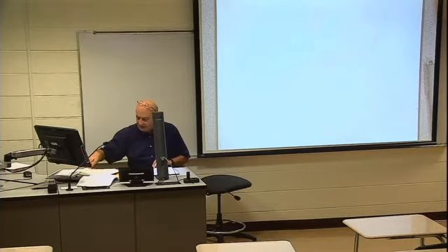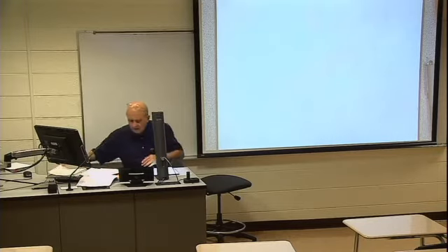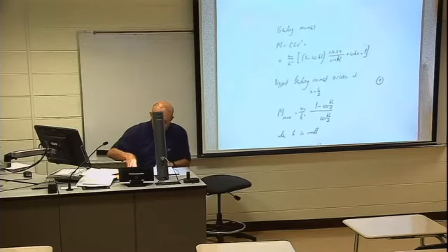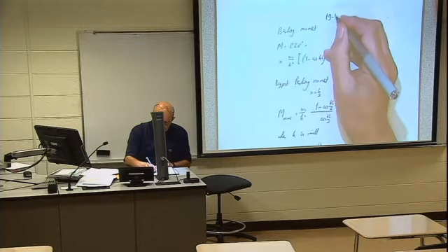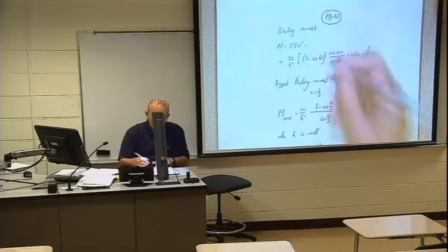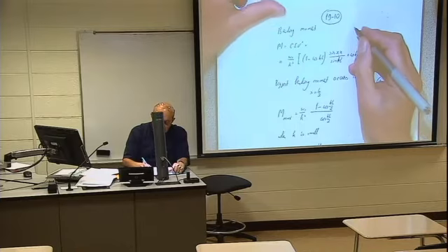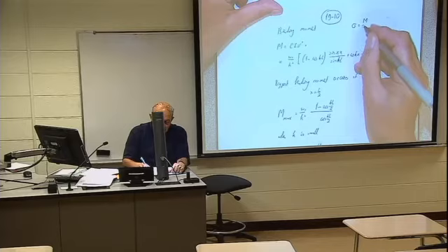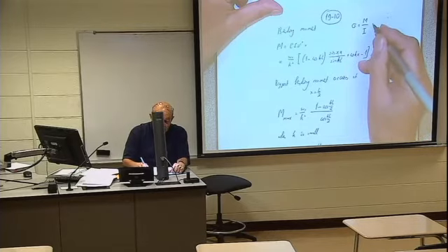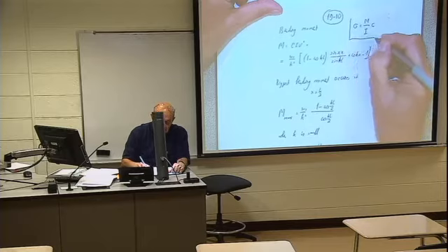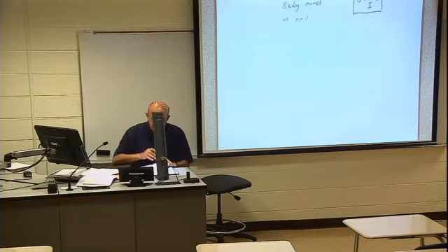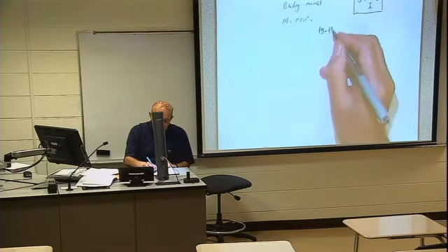So let us find, so we found the displacement. Let us find the bending moment, 1910. Why do we want bending moment? Because from bending moment, I can calculate sigma, bending moment divided by moment of inertia times c. Okay, just I will make like this, 1911.